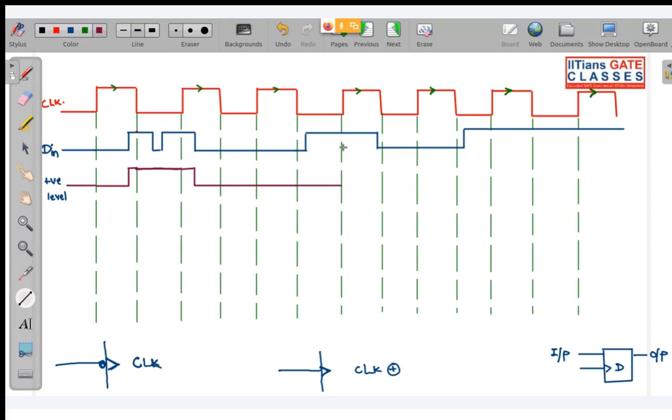So 0. Now look, at the starting of this positive level, output is 1. So immediately your D flip-flop will switch to higher state and it will stay over here until this point. There is a change in input from high to low in your positive level. So you are going to come back over here once again, and you are going to continue with this state.